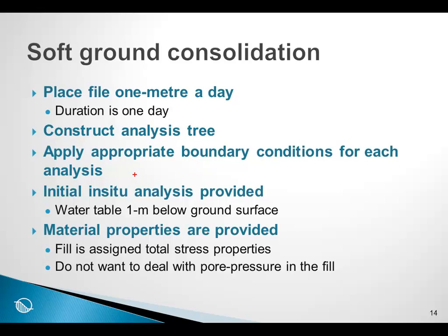The fill material will be treated as a total stress material because we don't want to deal with the pore water pressure in the fill. We could assume, for example, that the fill material is very granular and the pore pressures are not of consequence in the fill, and one way of doing that is to use the total stress properties for the fill.